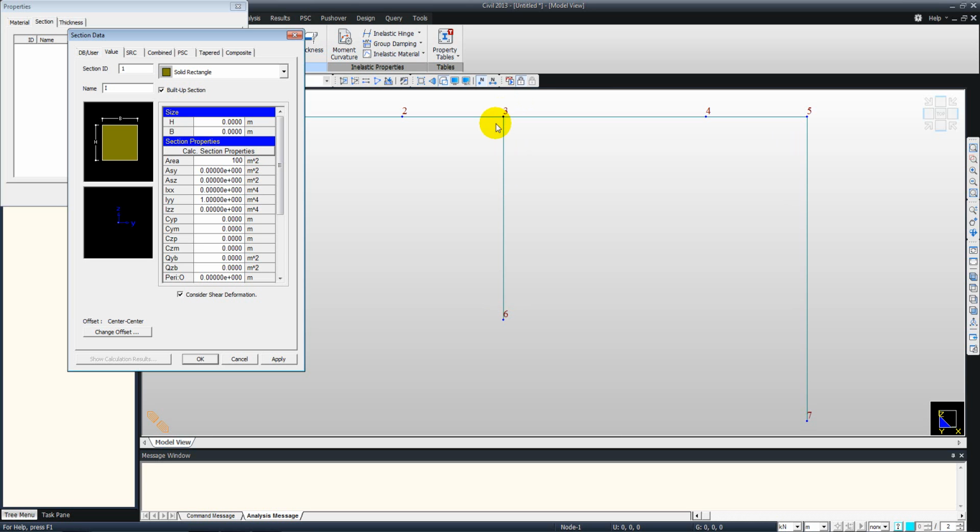That's why we'll keep the IYY or the moment of inertia as accurate, but area we can play around with some higher value, so that we get the more accurate representation of the bending moment diagram without any other interaction of the actual forces or deformations due to the column settlement, etc. So we'll keep this as 100 area, and IYY is 1 meter to the power 4.